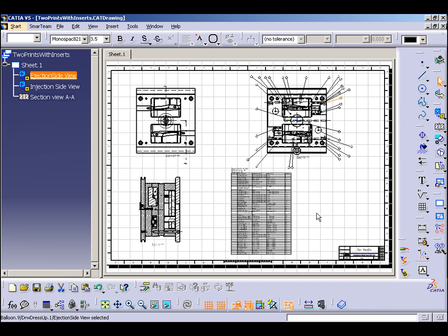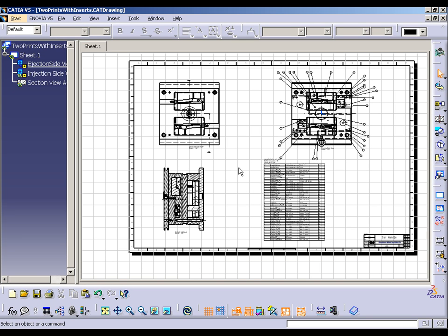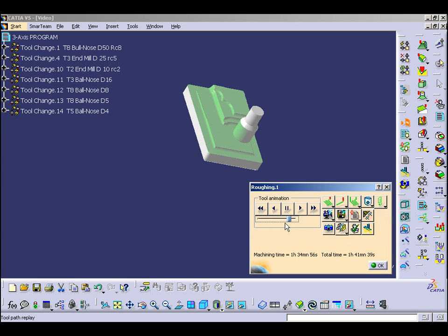The tool template includes not only the 3D assembly, but also drawings, which are a starting basis to help reduce the amount of work to define the 2D sheets for the new project. Thanks to the single CATIA V5 infrastructure, the machining operations are natively defined and integrated in the same tree structure as the geometry. 3-axis operations like roughing can be conveniently checked by video simulation.